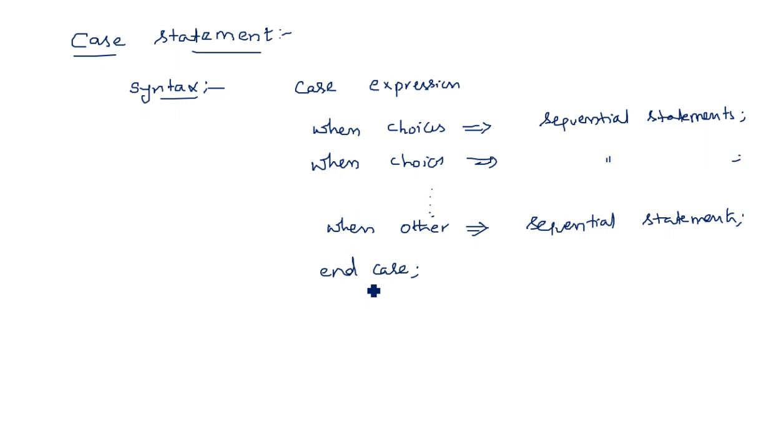The case statement selects one of the branches for execution based on the value of the expression. For example, in a multiplexer, case S is when, let us consider a 4x1 multiplexer. A 4x1 multiplexer has two selection lines. So 00 should be kept in quotations.